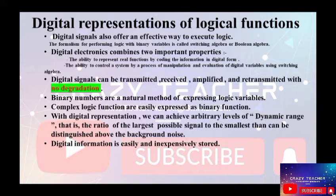At the receiving station, if you get some intermediary value, say minus 5 volt, you can say that minus 5 volt is close to minus 12, so that can be taken as 0. Even if I have got some values degraded, digitally the value is not degraded. We can still take it back to 0.